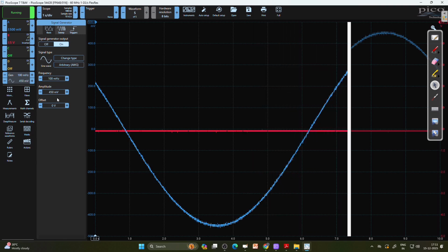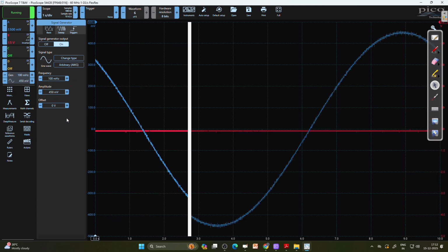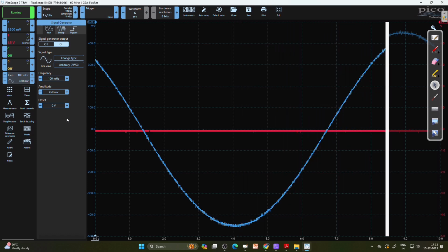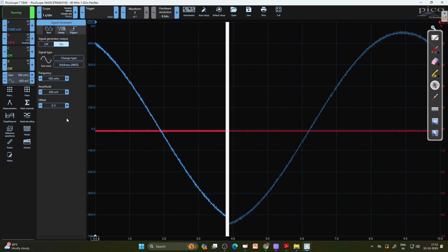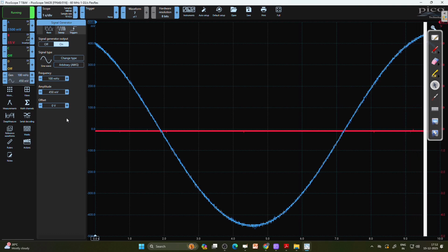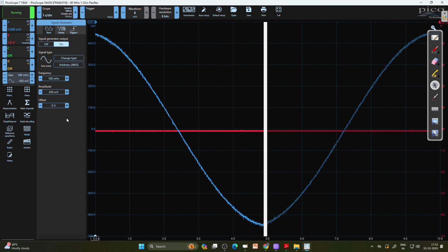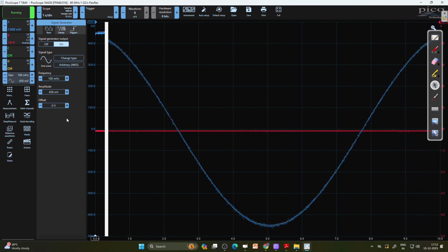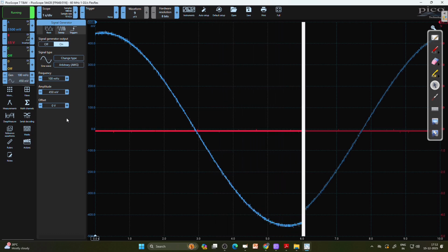Nothing. That is good. But this voltage is far too low to drive the piezoceramic stack. It's just a control signal we put into the high voltage amplifier. Exactly, thank you. And the high voltage amplifier has an amplification of factor 200. So from 0.45 volts, I get 90 volts. So now I go between plus 90 volts and minus 90 volts. And since the distance of the electrodes is very small, far below 100 micrometers, this is a field above 2 kilovolts per millimeter, which was your question.